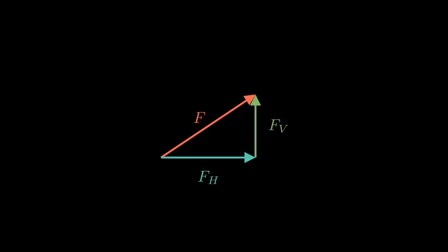When we calculate fluid pressure against a flat dam wall, the math is straightforward because the pressure vectors all point in one direction. But what happens when that surface curves? On a curve, the push of the water is constantly changing its angle. Solving this directly requires grueling calculus at every point. To save our sanity, we use a beautiful trick from physics: decomposition.